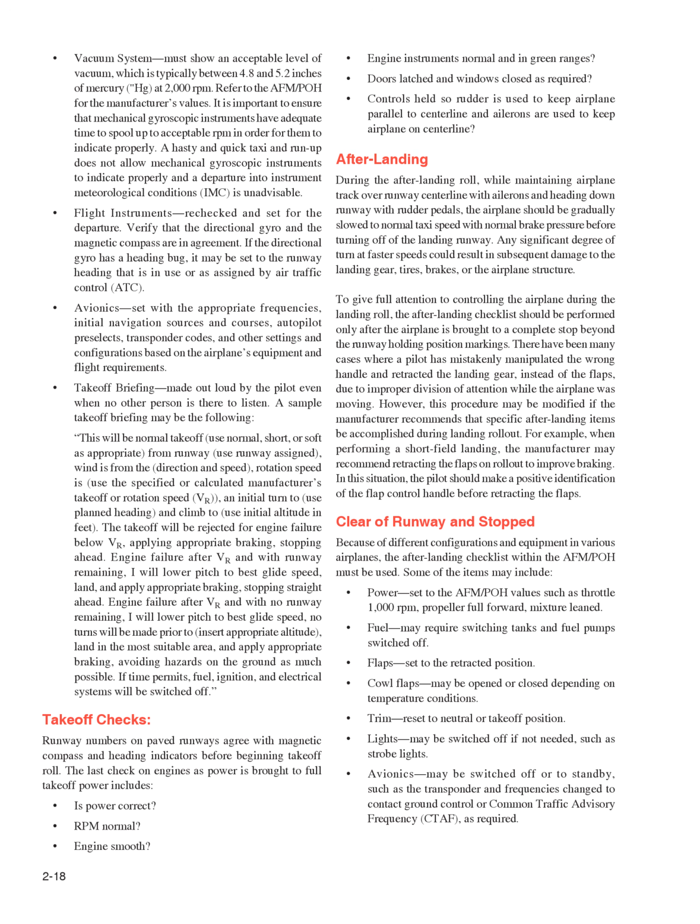Fuel, may require switching tanks and fuel pump switched off. Flaps, set to the retracted position. Cowl flaps, may be opened or closed depending on temperature conditions. Trim, reset to neutral or takeoff position. Lights, may be switched off if not needed, such as strobe lights.